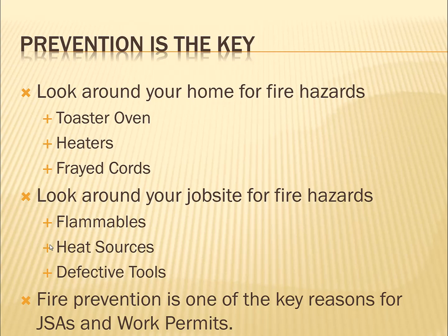And so work permits, you're not going to see them on a general construction site, but you will see them in the plants. They're required. OSHA requires the petrochemical industry and other high hazard work that's classified and specified as high hazard work by OSHA, that the host company that's running the plant have and enforce a work permit system where nobody can do anything without a work permit.